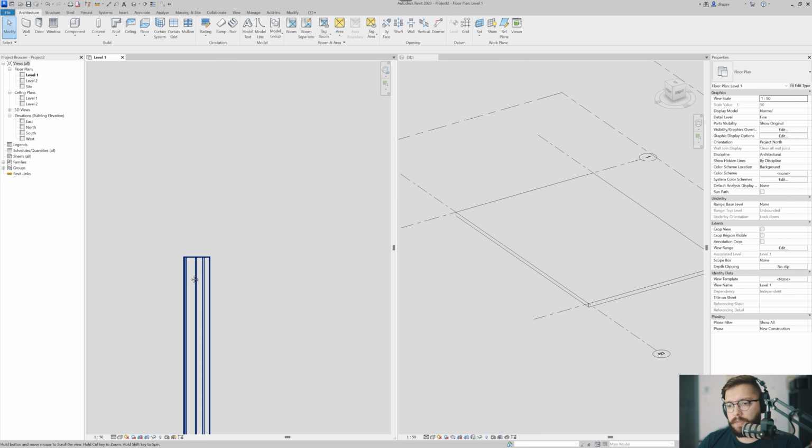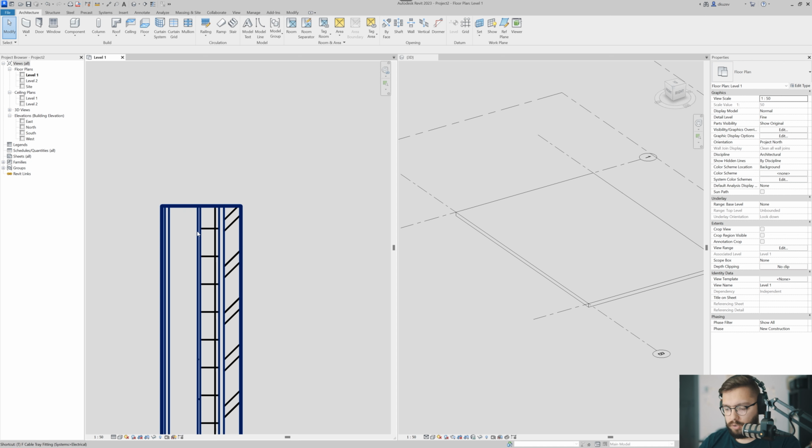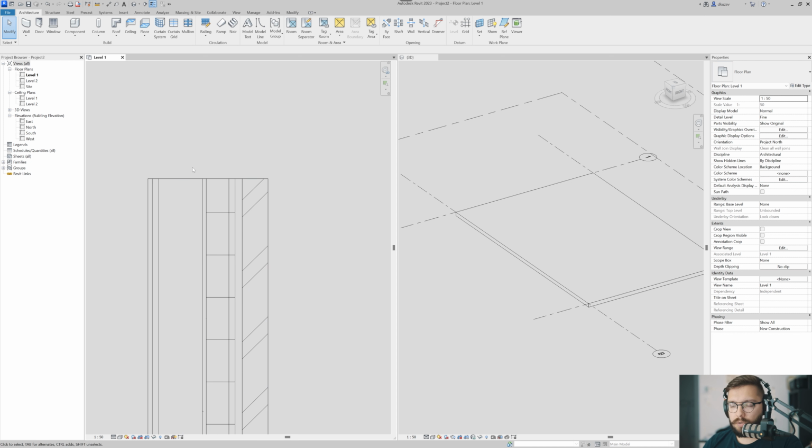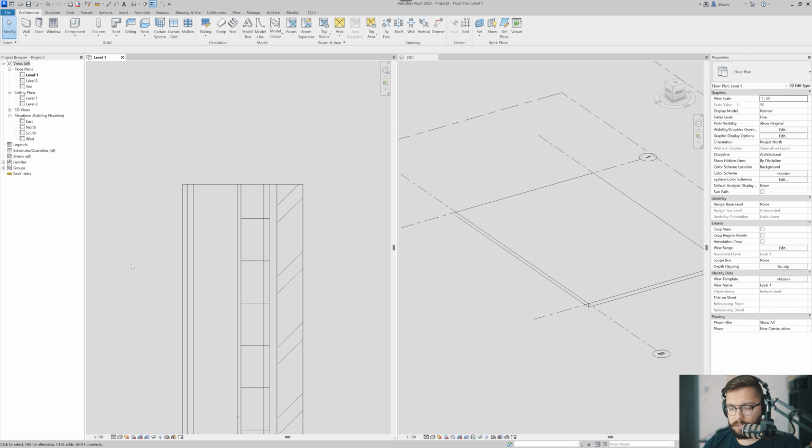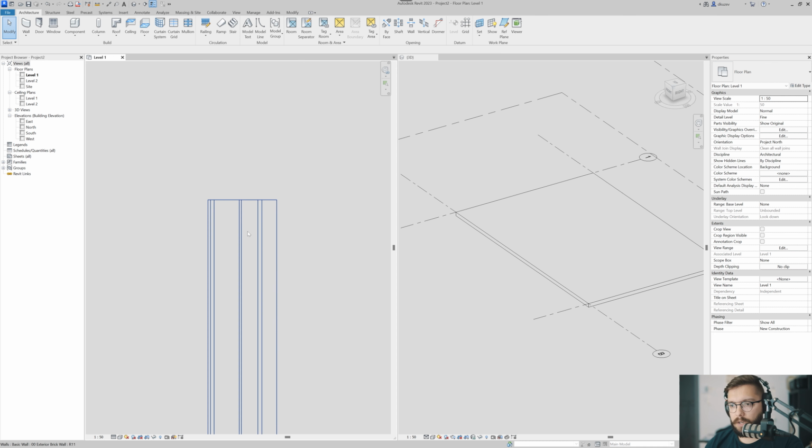And so the thing is that in a concrete building, what you're looking to do, by the way, I just hit TL. What you're looking to do is to align. So this is the outside here of the wall on the right, and this on the left is the inside. In a concrete building, in general, that is, what you're trying to do is you want to make sure that you align the edge of your slab with the outside of your wall, well, with the outside of the gypsum board, right? So that you can actually have a continuous surface from the columns to the slab edge to the gypsum board, so you can have one continuous surface to put your insulation on. So this is kind of like the whole logic.